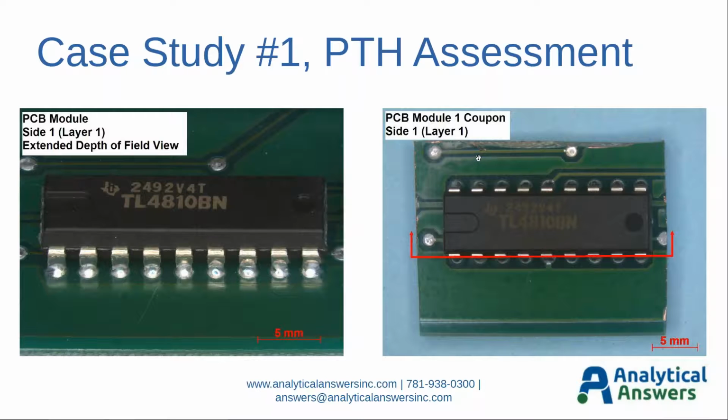And we want to make sure that we use extraction techniques that are recommended. I've seen cases where people may use a punch and die setup, which would not be recommended. In this particular case, I've used a Dremel tool to carefully remove and cut out this coupon. And again, I paid particular attention to make sure that I was several millimeters away from the region of interest here.